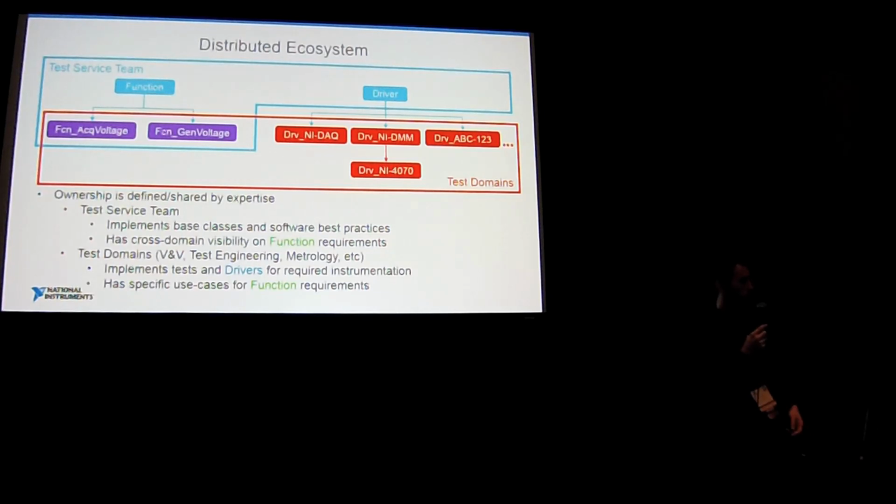Correct. I'll talk a little bit about some of the unique things we have in the RF world. As an example, we have acquired RF power, and generally to get the accuracy, we'll use a power meter, but they don't have the dynamic range, and they're generally pretty slow. So we can use a spectrum analyzer to make a similar measurement. This goes back to an example where you would have an untraditional instrument working with a different type of measurement.